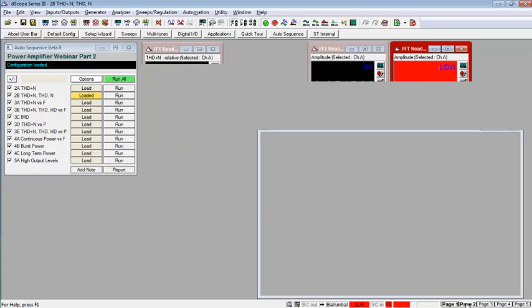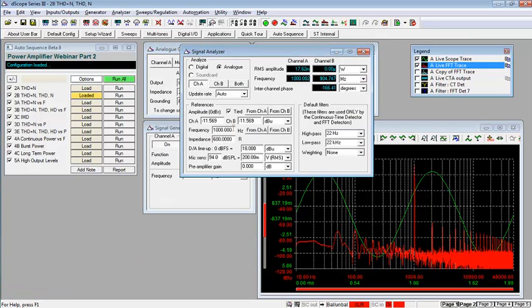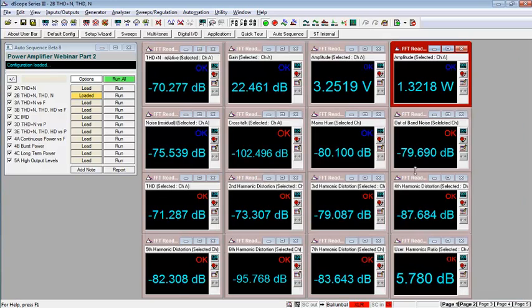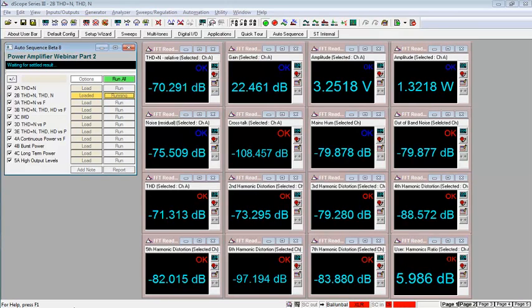So what I need to do here is to go into my analyzer and, oh yes, look, I've got the default value of 600 ohms in here. If I change that to 8 ohms, watch what happens to the RMS reading here. 17.6 milliwatts at the moment. Change that to 8 ohms. Power equals V squared over R. R has changed, therefore so has power. And if I go back to page 1 now, everything looks okay. I can run my test to get my automated limit checking here, and yes, we have a green light now. The test has passed.